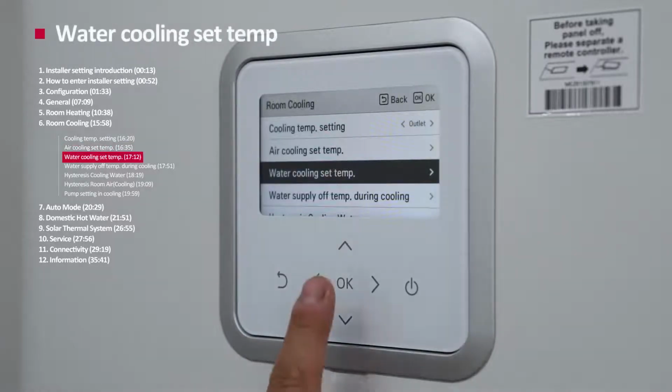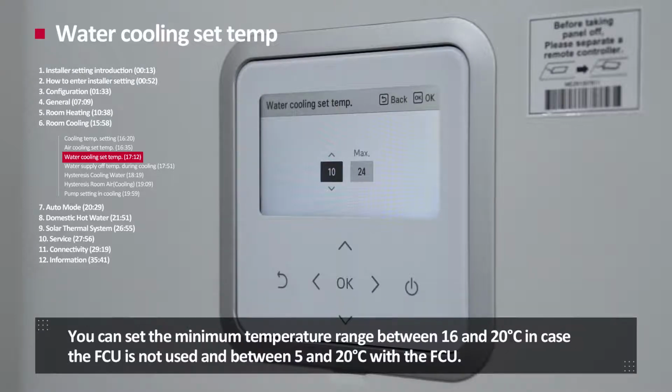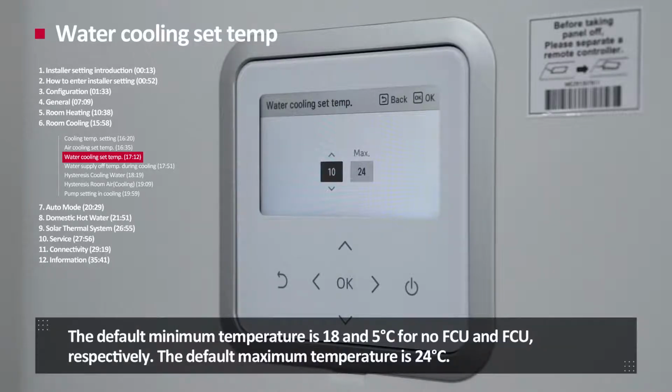Water cooling set temperature. If your cooling mode is controlled by water temperature, you can determine the maximum and minimum temperature by using water cooling set temperature function. You can set the minimum temperature range between 16 and 20 degrees Celsius in case the fan coil unit is not used, between 5 and 20 degrees Celsius with the fan coil unit. The default minimum temperature is 18 and 5 degrees Celsius for no fan coil unit and fan coil unit respectively. The default maximum temperature is 24 degrees Celsius.